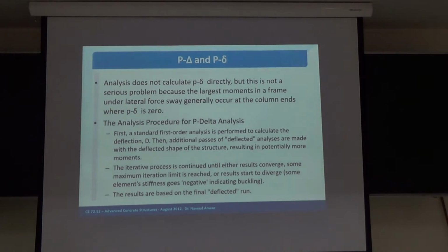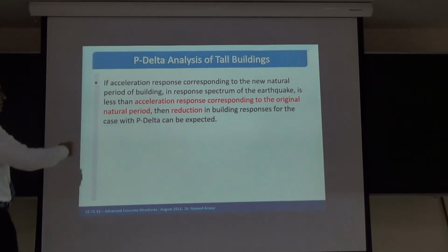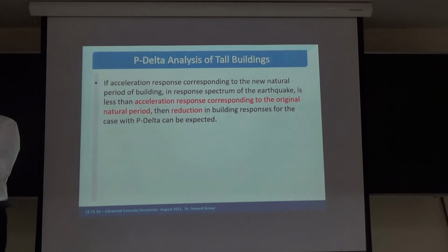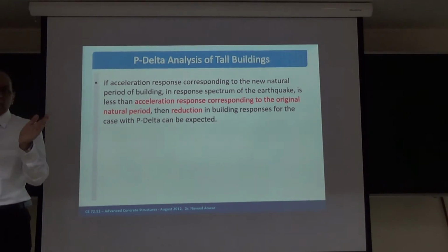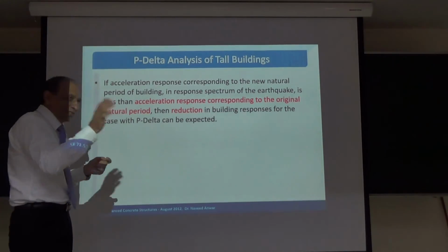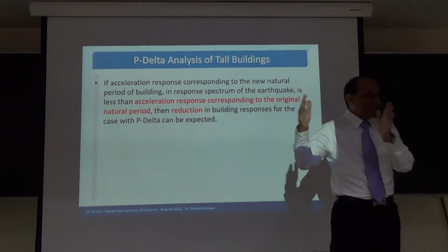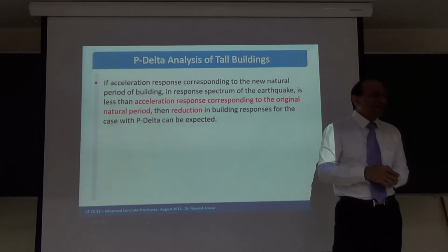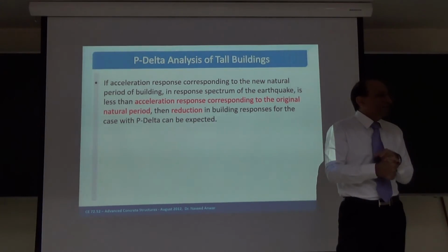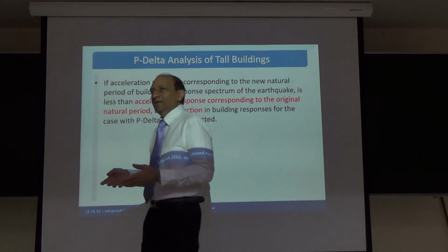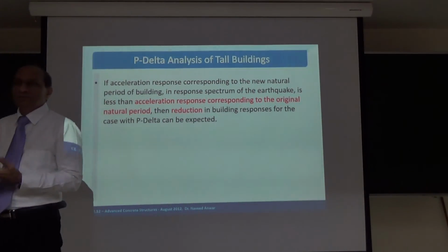Please read this. Yeah, this is what I was talking about, the acceleration response. Sway is related to this: if there is too much sway, you have to go too far, and acceleration will be very high. So people will feel it, right? That's why it needs to be limited. The acceleration of the building moving, speed, velocity, and also the amount of displacement, they need to be controlled. In fact, this is one of the key controls in building design, sway. Everything ultimately comes down to sway control.